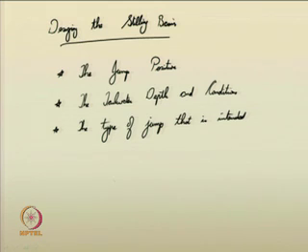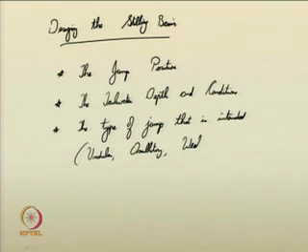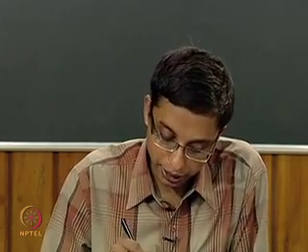You have studied the types of jumps, right? For example, undular, oscillatory, steady, weak, steady, strong. Various types of jumps you have studied earlier. So, which type of jump you intend to provide at that location is also quite essential while designing the stilling basin. The jump position, we will deal with that first today.